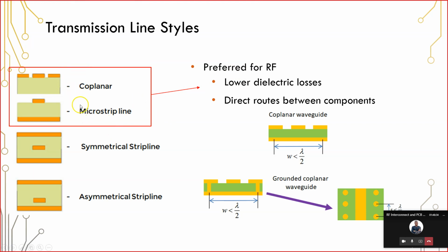In these two particular transmission line geometries, when the signal is traveling between these two conductors, on this interconnect, the electric field and the magnetic field exist around this trace. So the signal doesn't really travel on the conductor. The signal is bounded by the conductor, and the current that exists on the conductor generates an electromagnetic field around this trace. So some of those field lines pass through air in these geometries.